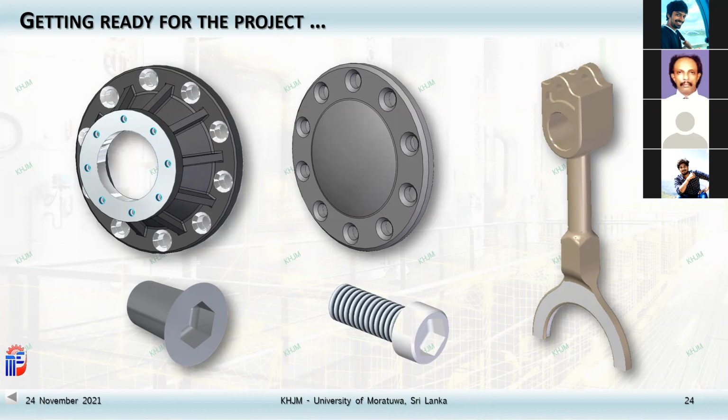And you see it is with a certain depth, not like one in the middle. And then there you should have a seal. Sometimes when you look for the seal, the seals are standard. The outer diameter of the seal is much bigger. When you try to match with your shaft diameter, the outer diameter is much bigger.